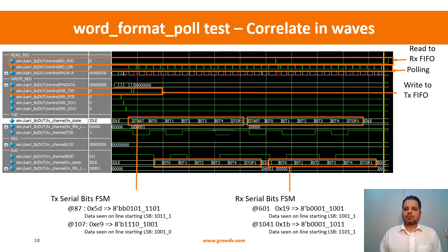and extract the stimulus. Why I am saying that is, even if I read the test, I will be seeing transaction.randomize. When I look at transaction.randomize, I cannot figure out what random values have been generated. To understand that, I have to look into the log files, and since there will be so many similar repeating statements, because I'm repeatedly generating multiple sequence items, I will see multiple prints, right? So I cannot sequentially read them.